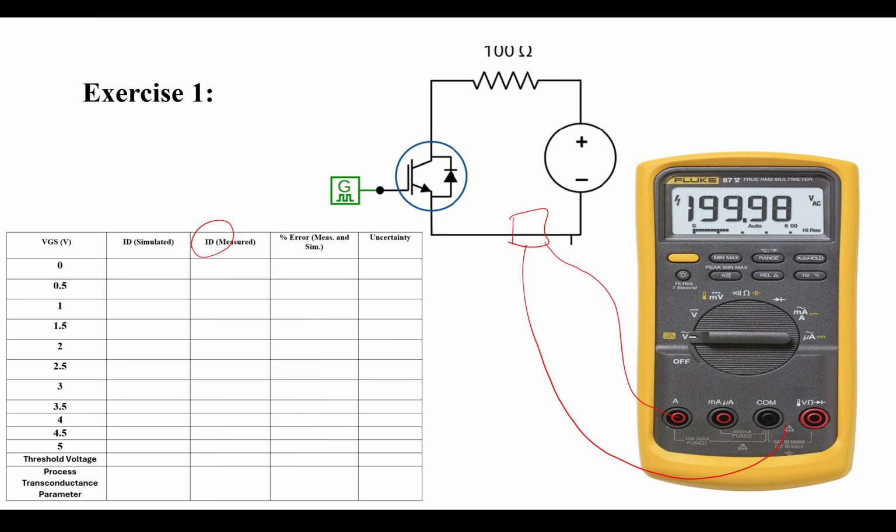And then here, you can use either the signal generator or one of the channels of your DC source, because you have 3 channels in your DC source. I believe this one is 5 volts, so you don't even need to use one of the 2 variable channels. You already have a fixed 5 volt channel 3 in your DC source.